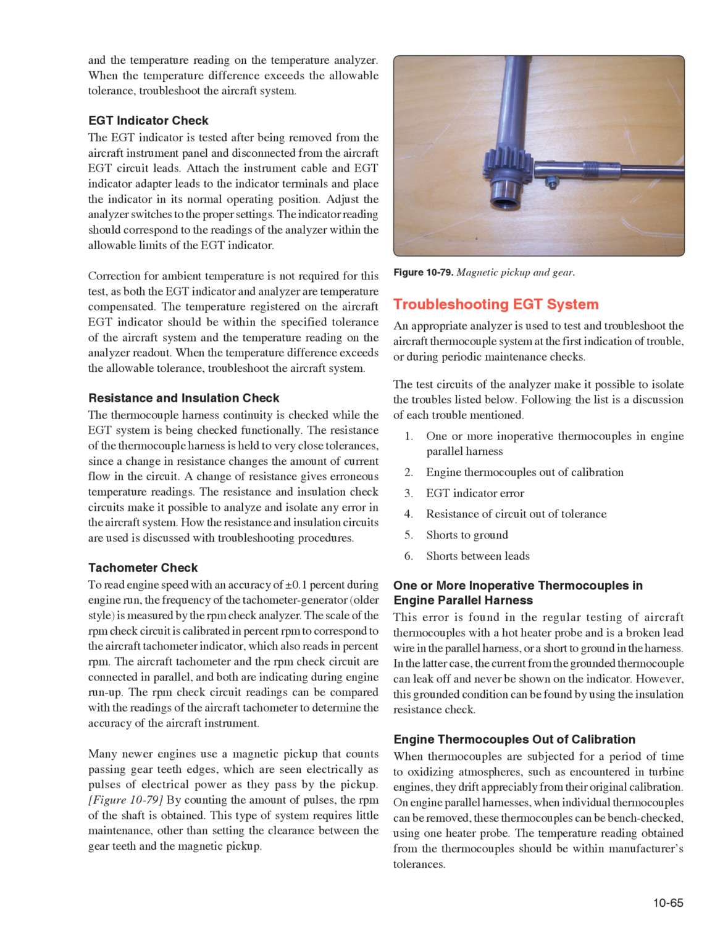Correction for ambient temperature is not required for this test, as both the EGT indicator and analyzer are temperature compensated. The temperature registered on the aircraft EGT indicator should be within the specified tolerance of the aircraft system and the temperature reading on the analyzer readout. When the temperature difference exceeds the allowable tolerance, troubleshoot the aircraft system.